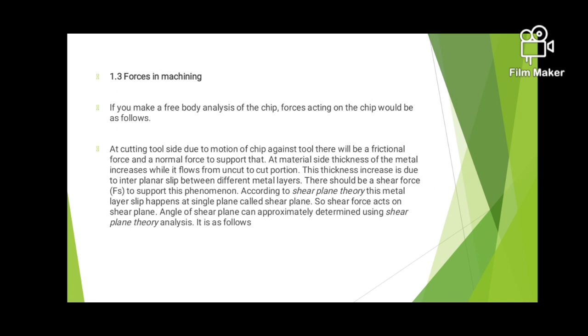The thickness increases due to interplanar slip between different metal layers. There should be a shear force to support this phenomenon. According to shear plane theory of metal cutting, chip formation happens in a single plane called the shear plane. So the shear force acts on the shear plane. The angle of the shear plane can be approximately determined by using shear plane theory analysis.